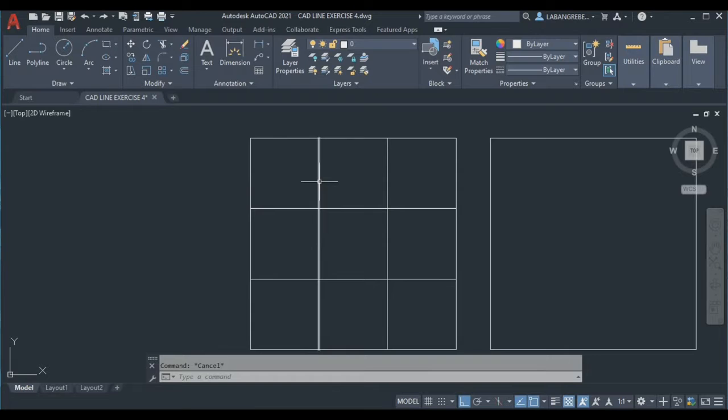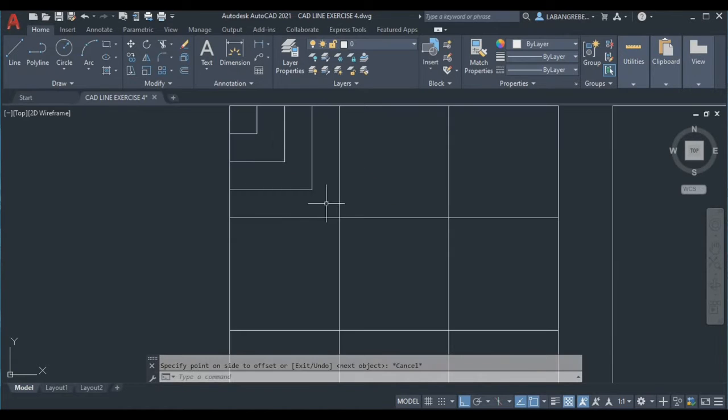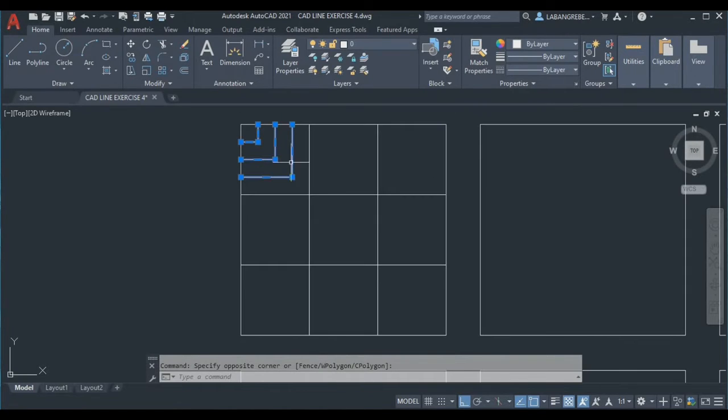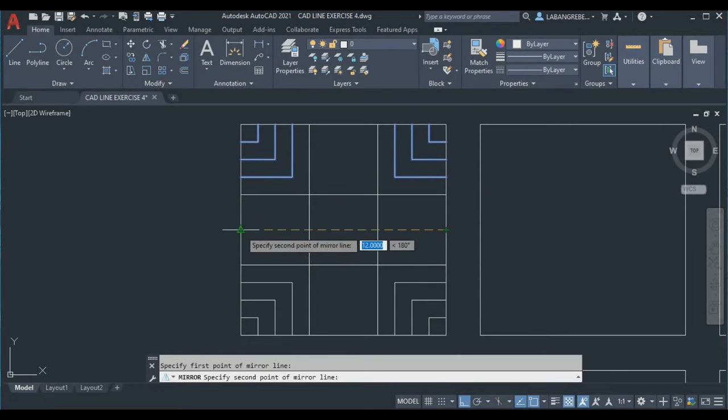Again, polyline from here, here, until here, and then select the line, offset by 1, then M, going here. Okay, and then if we select this one, we're going to make a mirror going here, and then select this all together, and then mirror it down here using this midpoint going down to this midpoint.